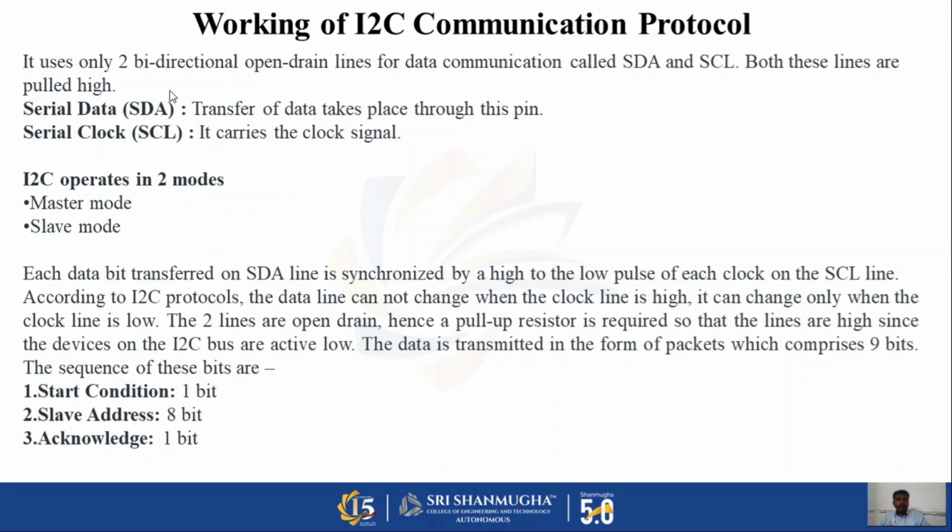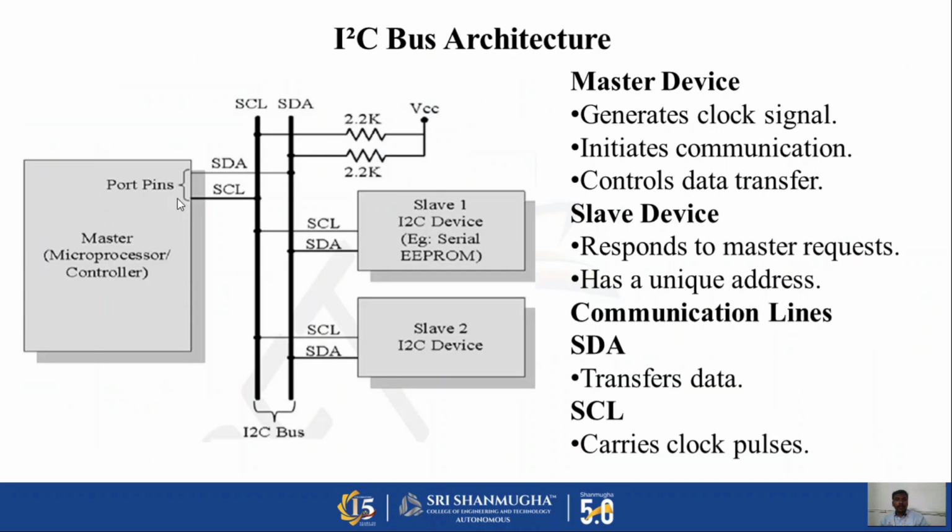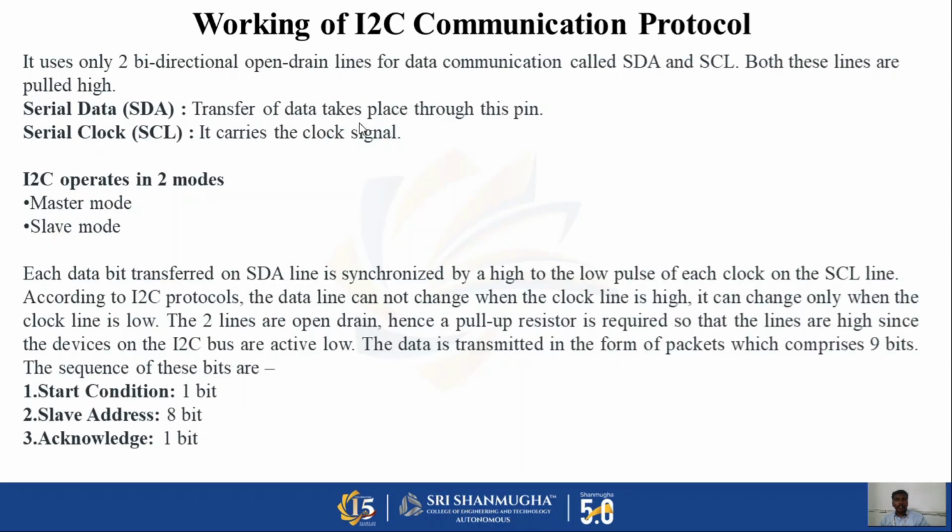The SDA and SCL lines are open drain lines. This means that devices connected to these lines can pull the line low, but they cannot drive it high directly. Therefore pull-up resistors are connected to both SDA and SCL lines. These resistors ensure that the lines remain at logic high when no device is actively pulling them low.